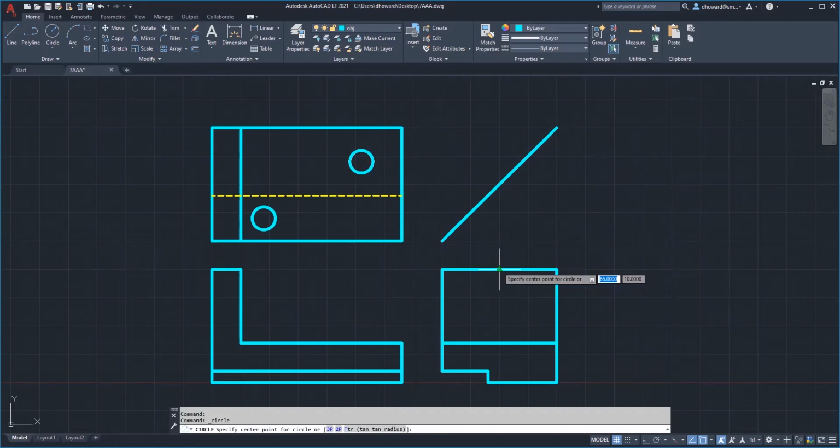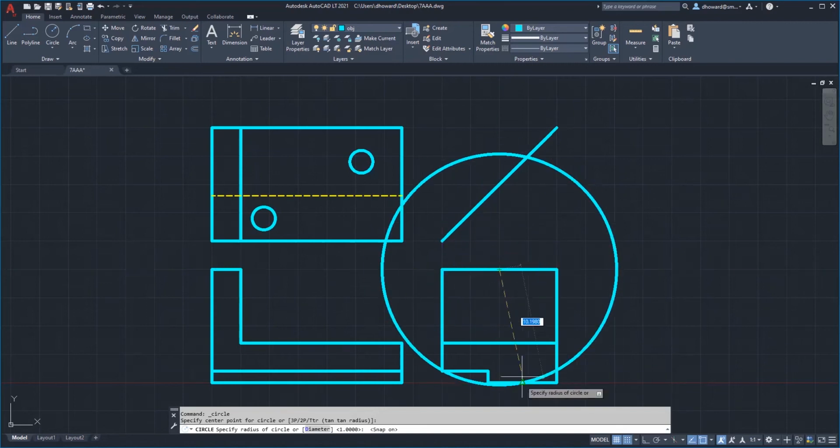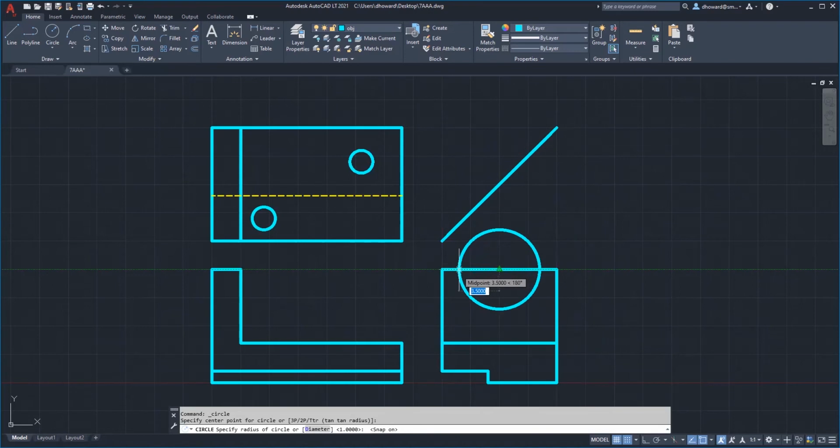And I'm getting that little icon that shows a little triangle midpoint. And that's because I have my object snap on. And I'm going to drag it out and click somewhere on the grid. Now I'm going to turn the grid on, F9, and grab pretty close to the edge. I think that's about right. My next step is to trim out what I don't need, TR, enter, and just get rid of that stuff.